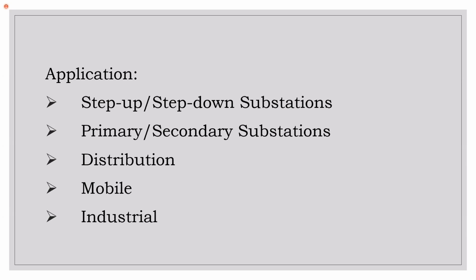The voltage at which you'll be supplying your energy will have certain requirements. In terms of the space in which you're operating, you may not be able to have a 138 kV line, for example, and I'm just throwing that out there. You may not be able to have a 138, but you can have a 69. So you have the 138 coming into the substation, you bring it down to the 69 and move it on.